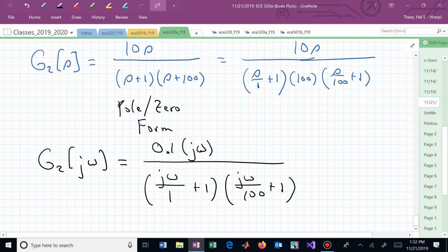So what's producing slope? We have how many factors? We have a constant factor of 0.1. That's always just flat, isn't it? What's log of 0.1? -1 times 20, so that's giving us -20 dB all the time. Then we have a 0 factor at the origin.